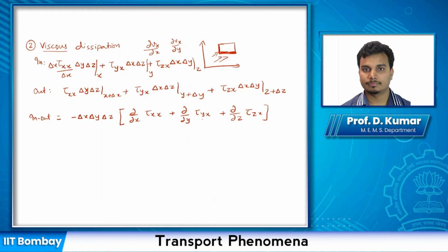Now we know, when we were just talking about one-dimensional flow, recall the initial discussion about Newton's law of viscosity, when you have a fixed plate and some fluid flowing, and your plate is moving at some v naught, so you have some momentum transfer in this direction. In this case, we saw tau yx is just minus mu dou vx by dou y.